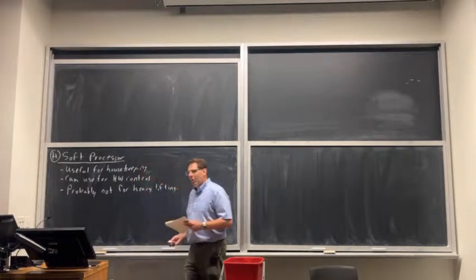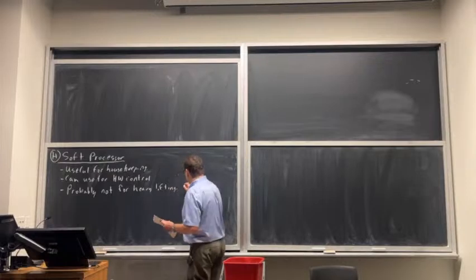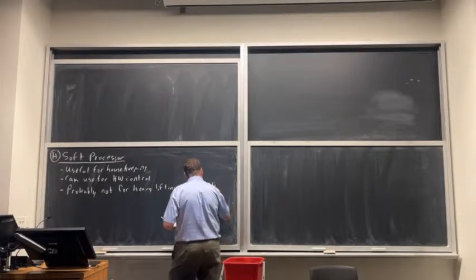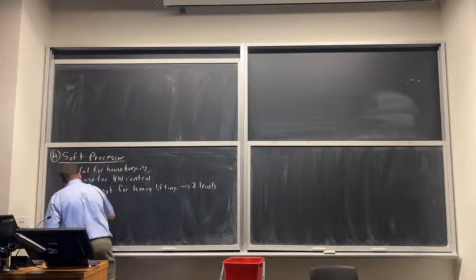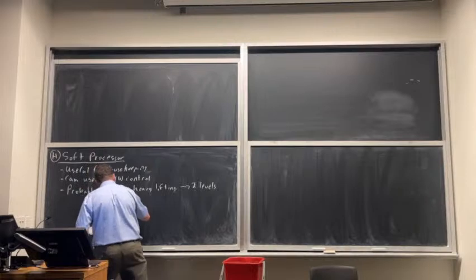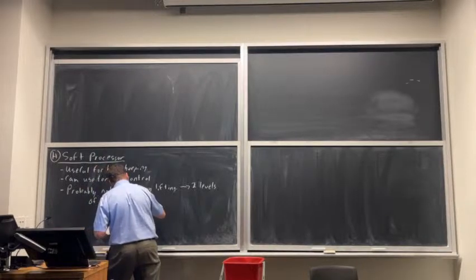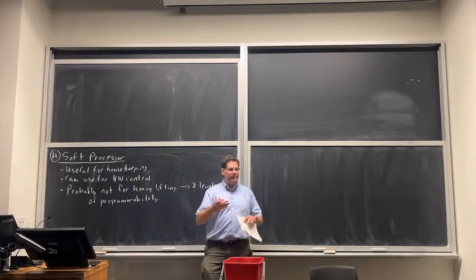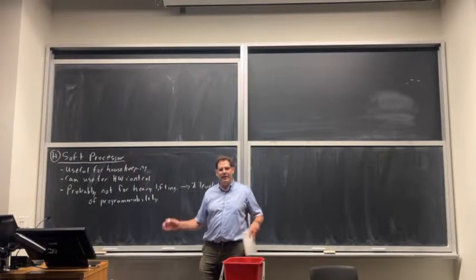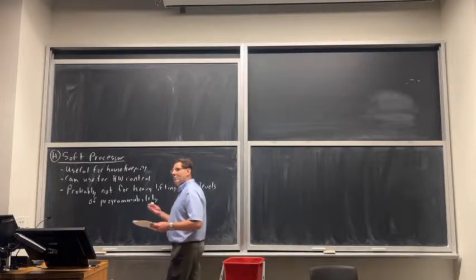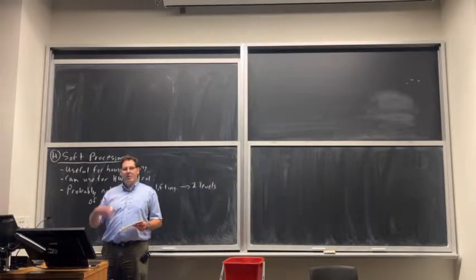And the reason why is you've got 2 levels of programmability. Your first level is the fact that you're using the fabric of the FPGA. You can rewire things, you can change the lookup tables. That's actually pretty expensive compared to just making the hardware.